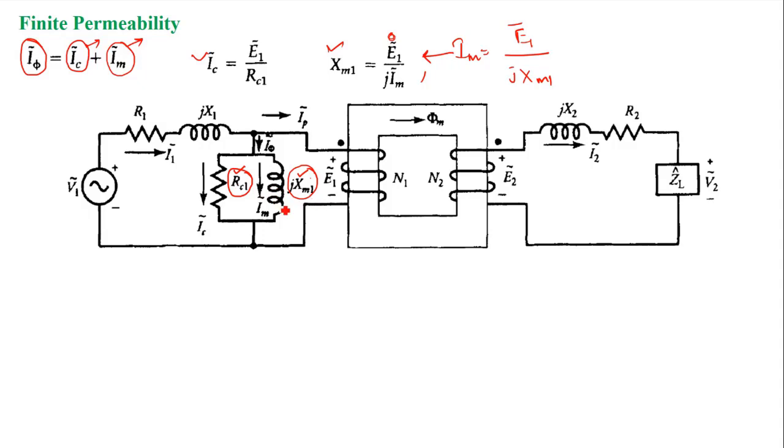That means all kinds of analysis we can do through this equivalent circuit. Any kind of steady state analysis in the transformer we can do through this equivalent circuit method. We are representing the core loss component, because core loss is a loss component, so heat will be produced in that. So it can be represented through a resistance.